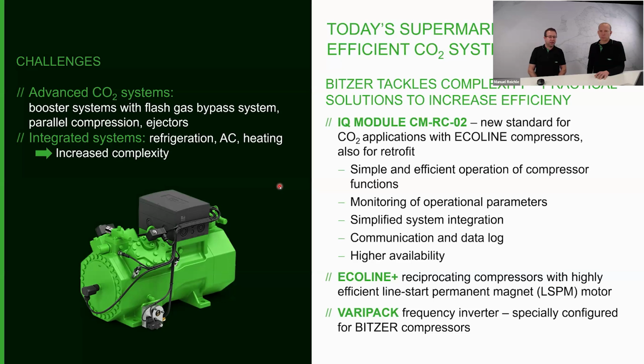At the end of the day, the oil separator is not separating 100% of oil always, so there's always a little bit of oil going into the system, which was not coming back because there was no running time. The service technician was then called for lack of oil in the compressor because of the oil management system. It could not feed back the oil. So what they did was refill oil, and the system was running.